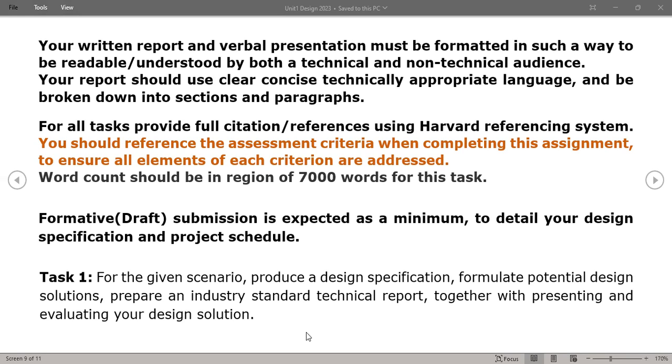And the way to do that is to use various standard techniques, which are proven standard techniques used in industry: a decision matrix, a weighted decision matrix, 3 columns with 3 different solutions, and you choose criteria, say 6 criteria, and you weight it 1 to 5. And at the bottom of the column, you add all the numbers up against the criteria, and the highest number is the chosen solution. Strengths, weaknesses, opportunities is effective as well.